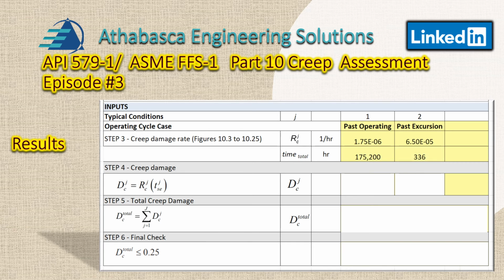So we put that together and we have a damage creep rate of 0.31 and a past excursion damage rate of 0.021. We put those two rates together, and we get 0.33. We do our final check and we find out that it fails. That means with certainty that a level 2 study has to be done.